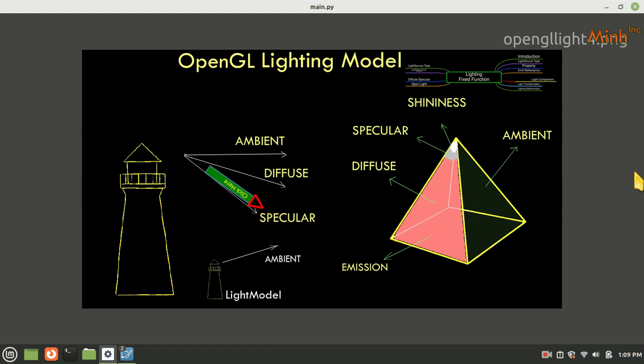Well, this is the OpenGL calculation method. Ambience makes sense, and diffuse also makes sense. But the light source also identifies that if light falls on the material, then please calculate through the specular component. And the material also, generally it is white because shining will be white. So that is the idea.